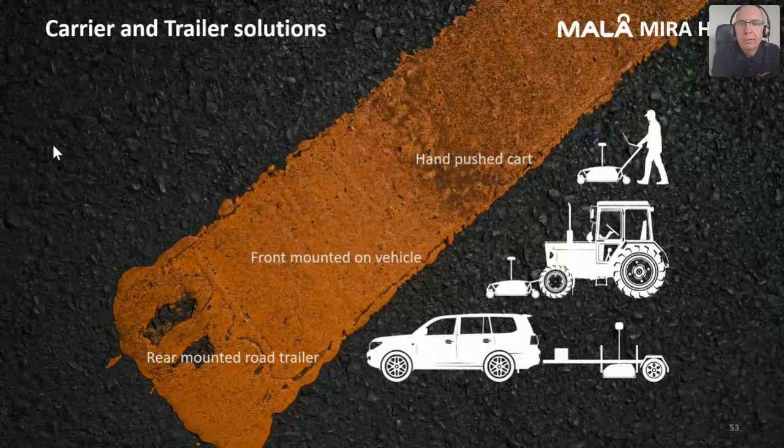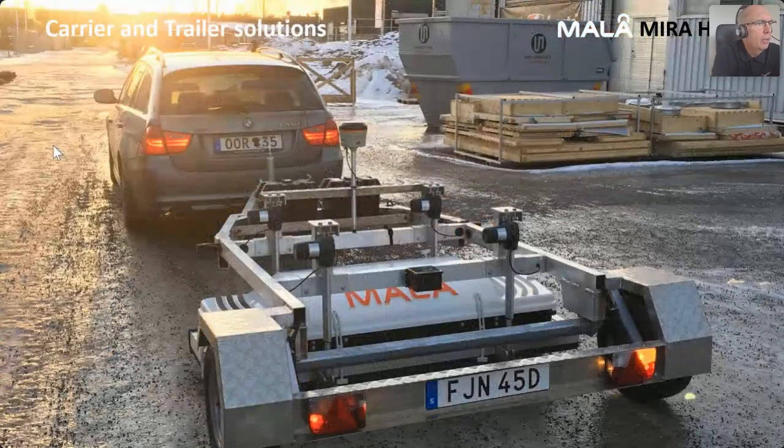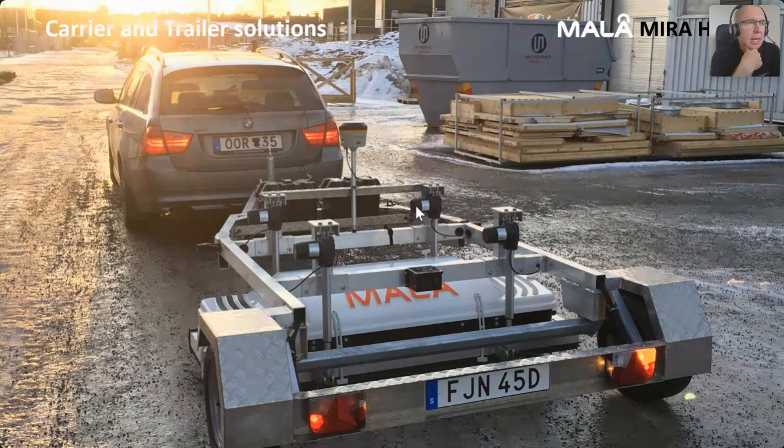We can front mount on vehicles, and we can also use the rear mounted road trailer on the back. Here's an image of one of the road trailers that we have, and on here you see the antenna in the center. We have a number of electrically operated winches. So what it enables you to do is remotely raise or lower the antenna. So if I'm driving to the site, I can raise that antenna up and run the system to the measurement area, to the site or the area of investigation. Now I can drop the antenna down and then start to take my measurements on there. So that's the trailer option.